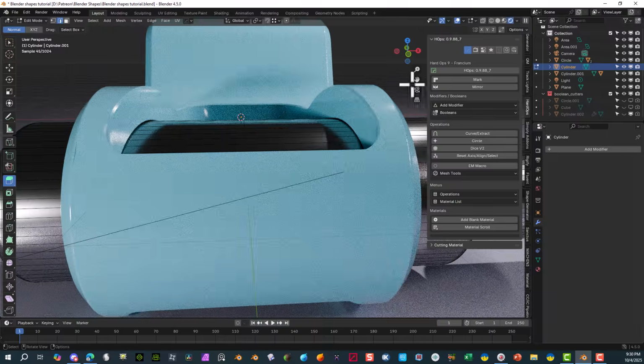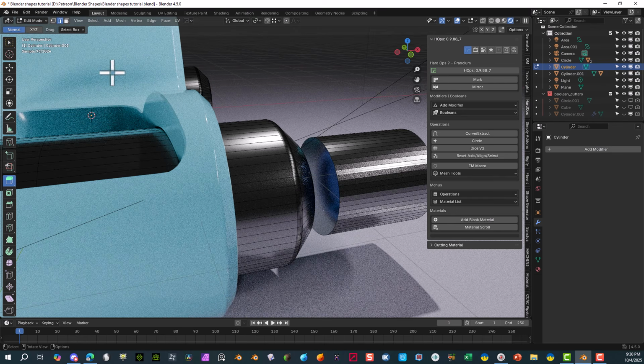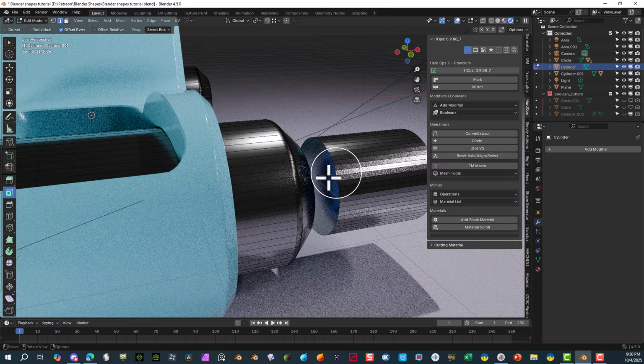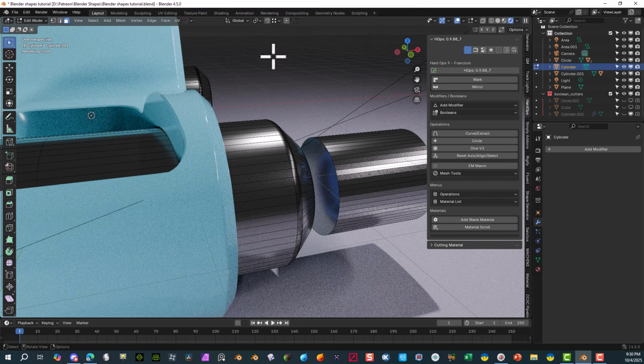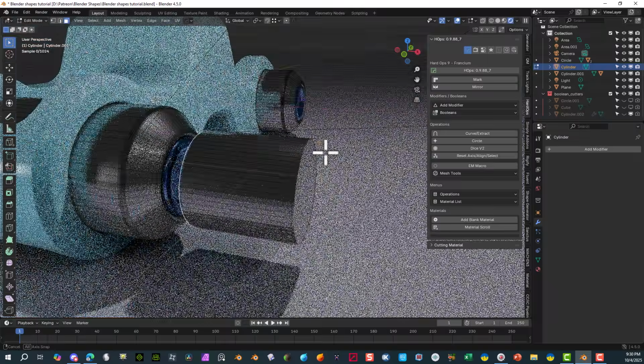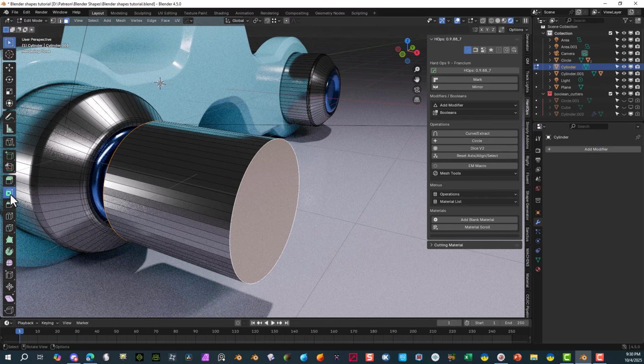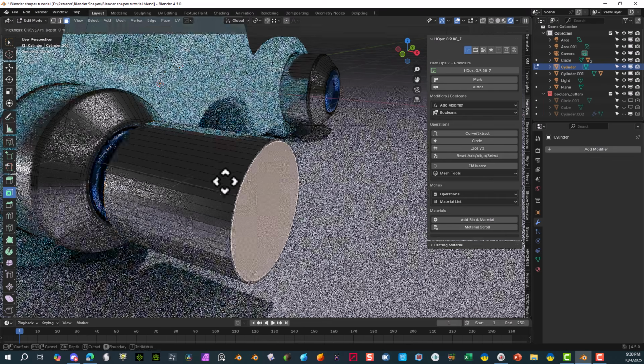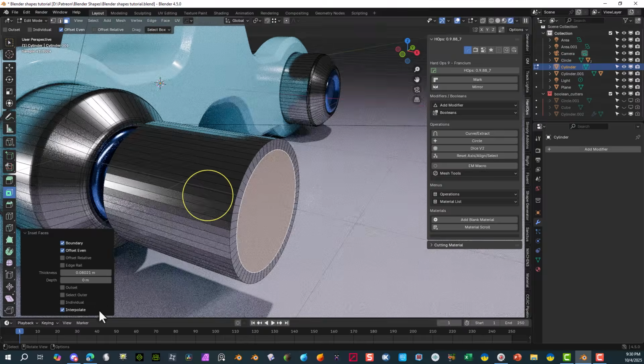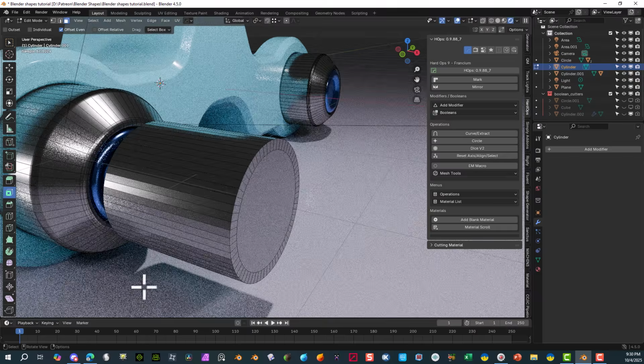Okay, we're going to do the same thing as we did before. We're going to actually create a hollow section in the cylinder. So we're going to first select the edge. But first we're going to do the actual faces here. So select both sides. And we're going to do the actual inset face and pull this inward. So right about there. And we're good with that.